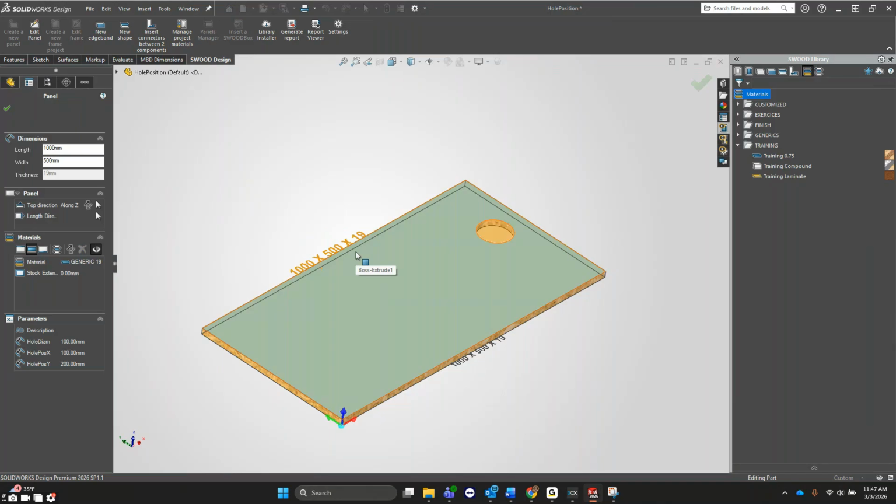Yeah, you'll use planes to position your panel and determine things like length, width, and that kind of thing. So the panel, you can think of it as like a building block of, let's say, a frame, which would be like a cabinet. And then, like I mentioned before, a panel is just like a SolidWorks part with a material applied on it. And basically that material gives a texture appearance and also drives its thickness.